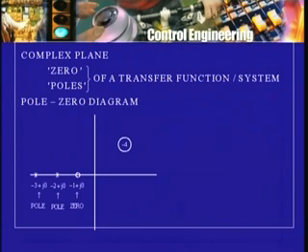So what do I have so far? I have a transfer function for which there is only one zero corresponding to minus 1, which means there is only one factor s plus 1, and that is in the numerator, mind you. For the denominator I have two factors, s plus 2 corresponding to this pole at minus 2 and s plus 3 corresponding to the pole at minus 3. So, the denominator is s plus 2 into s plus 3.